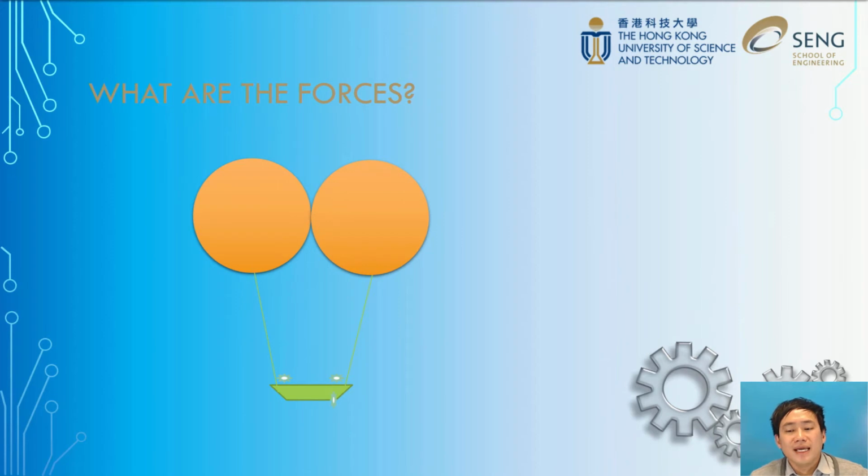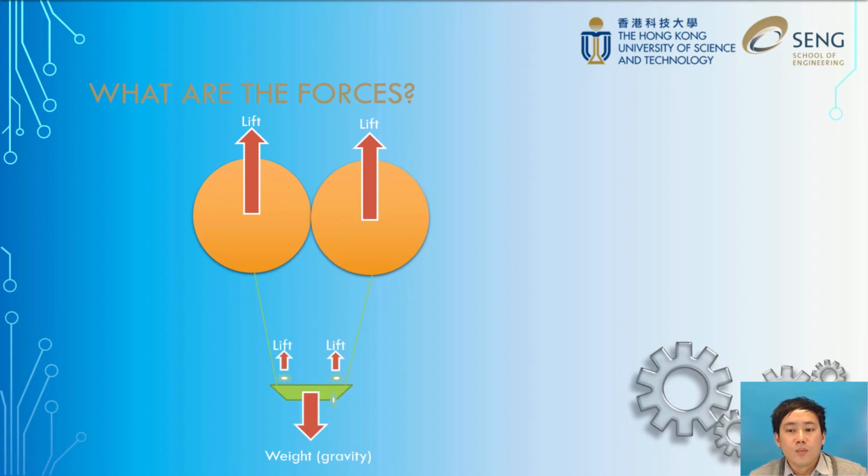So let's come back to the airship that you're going to build in this course. The typical forces acting on the airship body are the lift force due to helium balloons, the weight of the airship body, and the motors and propellers, which will generate lift forces for taking off and thrust for general movement. With translational movement, there will also be drag force caused by the air particles.